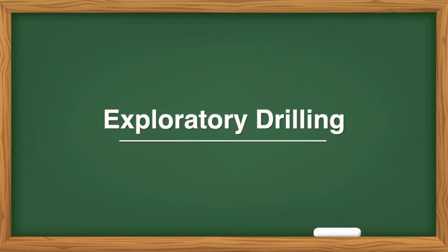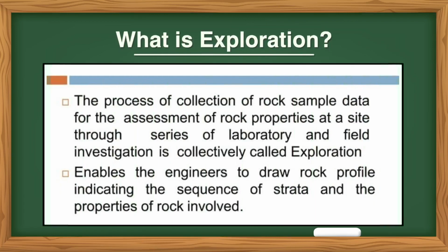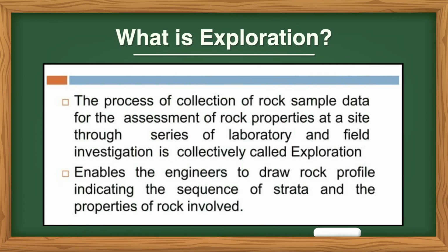Today I will discuss lecture number 2, exploratory drilling. So, what is exploration? The process of collection of rock sample data for assessment of rock properties at a site through a series of laboratory and field investigations is collectively called exploration. It enables the engineers to draw a rock profile indicating the sequence of strata and the properties of rock involved.